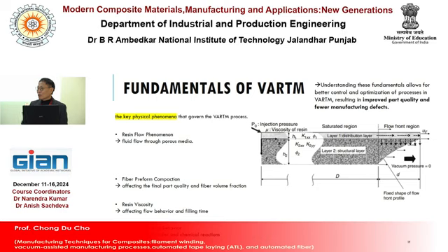If you can use a simulation, you can know the rough optimization point in advance. From that spot, you can reduce the number of trial and error runs of VARTM practice. Right? That means it can save your time and it can save your money.